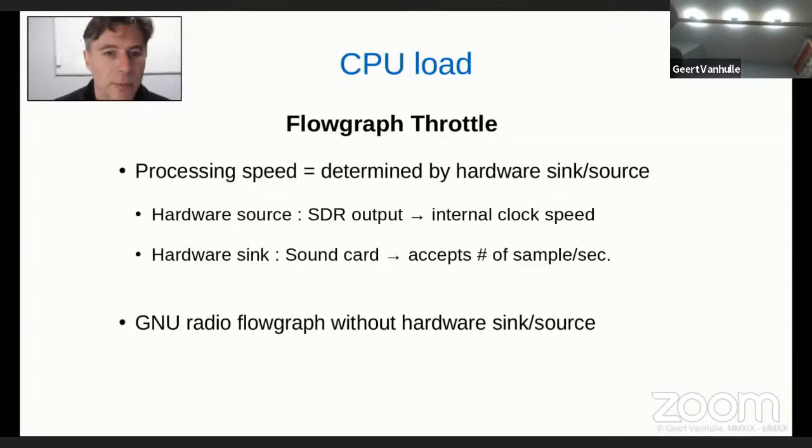Well, at the maximum speed my CPU allows. So if you would run a flow graph like that and check your CPU load, it will go up to 100% and even more, depending. Some cores will even be overloaded, but you will go up to 100% load of the CPU, even though it's not necessary. So it means that although the sample rate is 1 megasamples per second, it's well possible that up to 10 megasamples per second are being processed, because the sample rate is metadata.